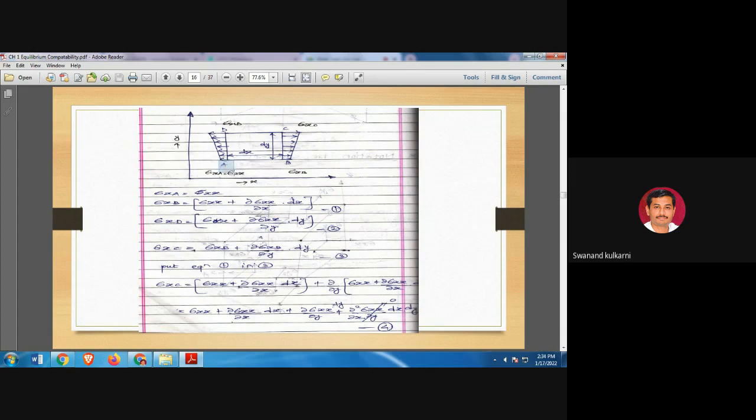So the reference point, as we have considered, is A. Then with respect to A, at point B, what is the stress? That stress is sigma xb. Then what is sigma xb? Sigma xb is considered to be sigma xx plus dou sigma xx. See here, it is a differential equation with reference to A. At point B, we are considering the differential equation, and that differential equation is with reference to x. So we are taking the differentiation of sigma xx with respect to x over this distance dx.